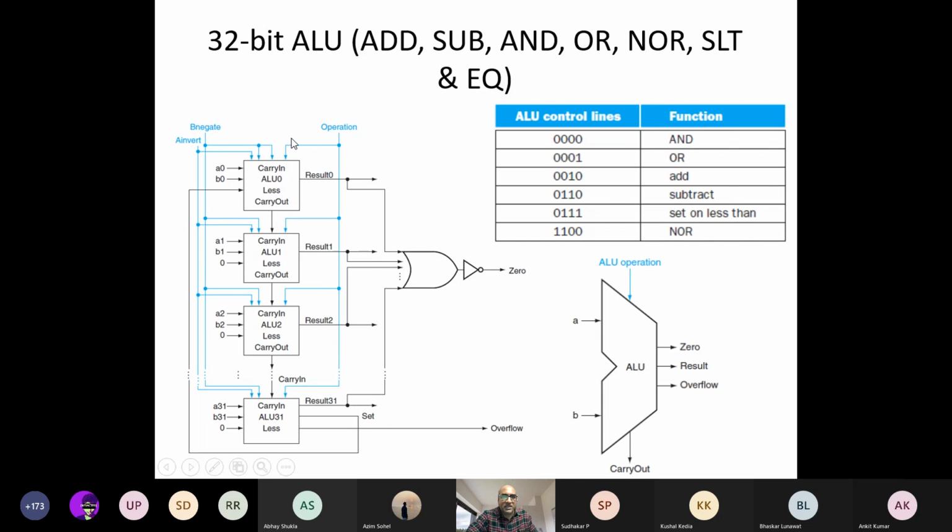I'm just saying that because when you try to implement a 32-bit or 64-bit adder, this is known as a ripple carry adder, because the carry will be rippled through all the stages. So if it's 32 bits, 32 gate delays have to be propagated. It has to propagate through 32 adder delays, each adder with whatever delay it involves. All these 32 adder delays will be involved in the resultant output, whereas the carry look ahead adder will not require all these things.